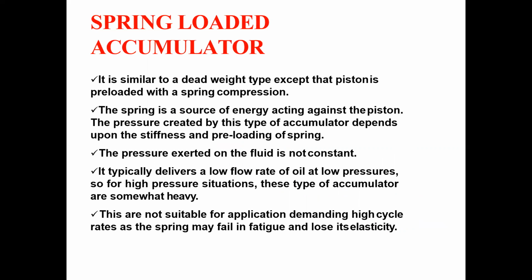The spring-loaded accumulator is similar to the dead weight type, except that the piston is preloaded with a spring compression. The spring is a source of energy acting against the piston. The pressure created by this type of accumulator depends upon the stiffness and preloading of the spring. The pressure exerted on the fluid is not constant. It typically delivers a low flow rate of oil at low pressure. For high pressure situations, this type of accumulator is somewhat heavy.